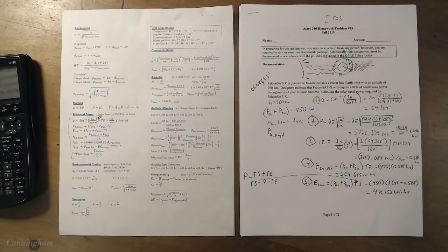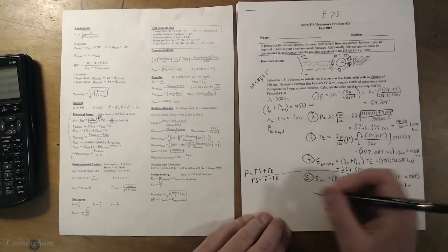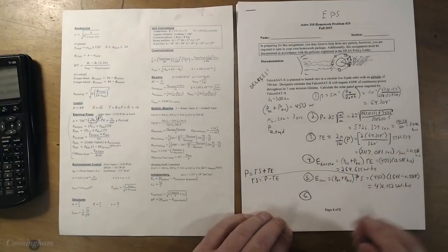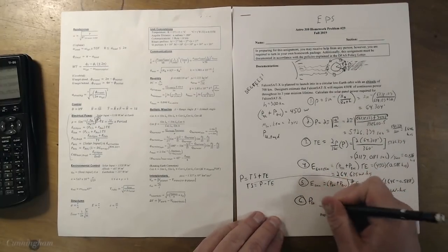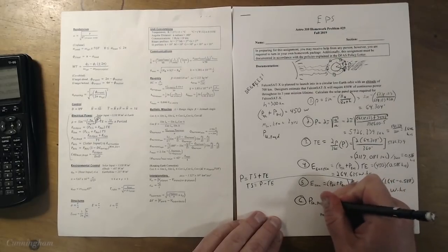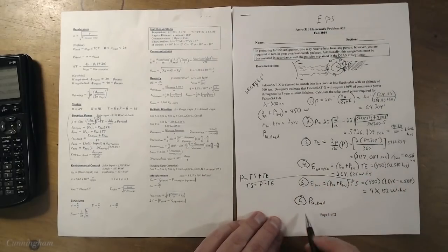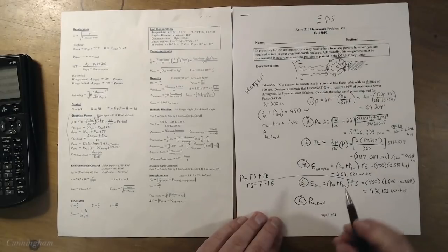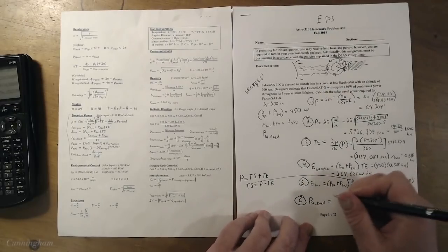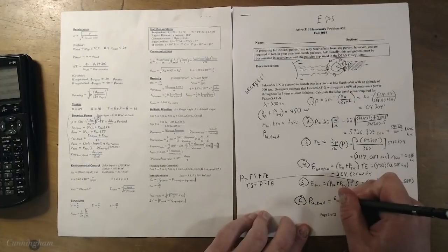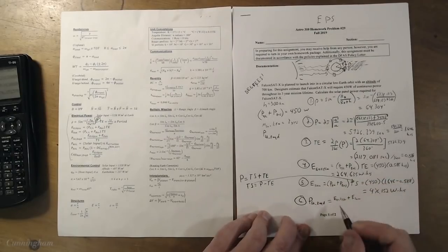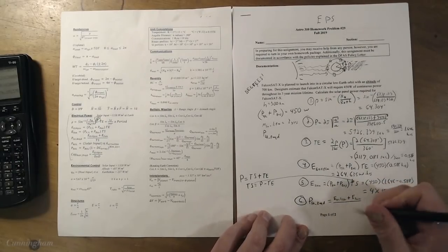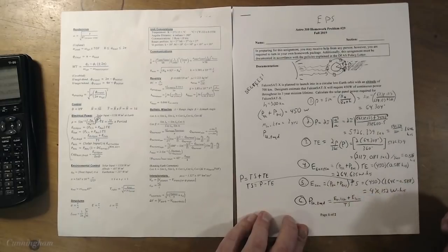Cool. All right, so step 6 here is, I would say, the last step. Look at all these little steps, but they're all little and they're easy. P_SA required: the power needed by the solar arrays is the energy that we have to use in eclipse plus the energy we use in the sun, all divided by the time we spend in the sun, right? Because we can only charge our solar panels in the sun.